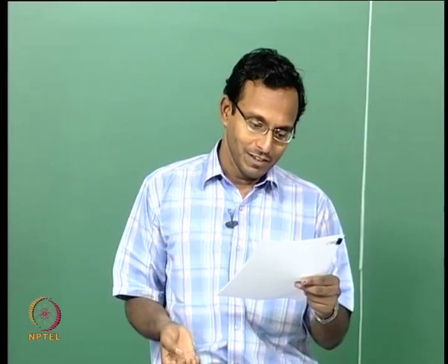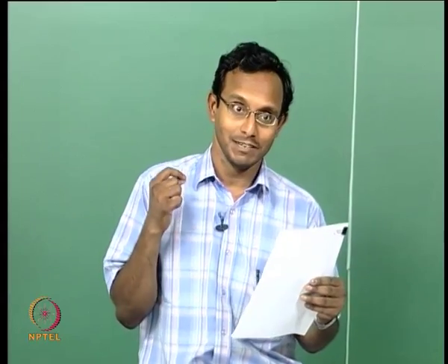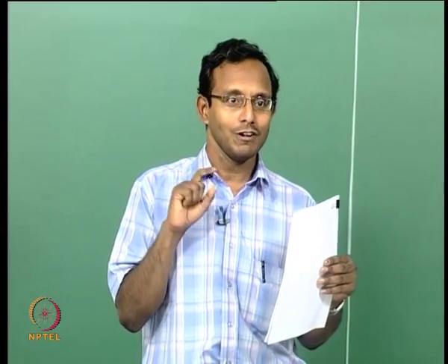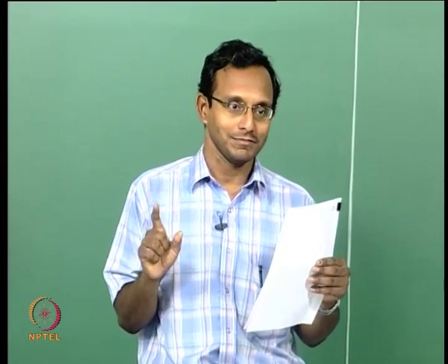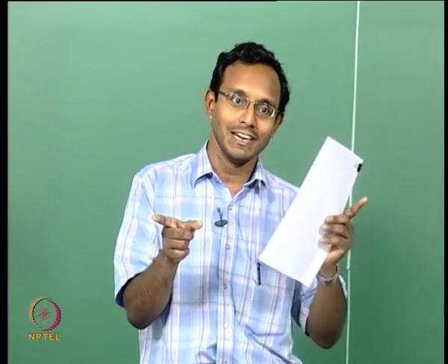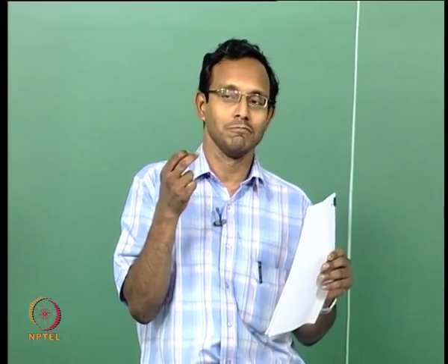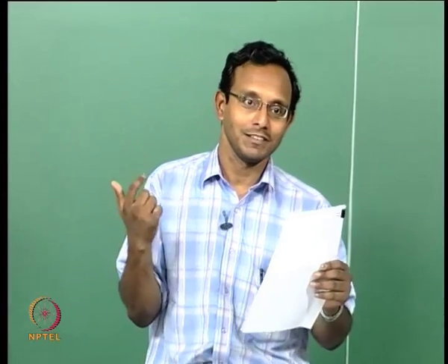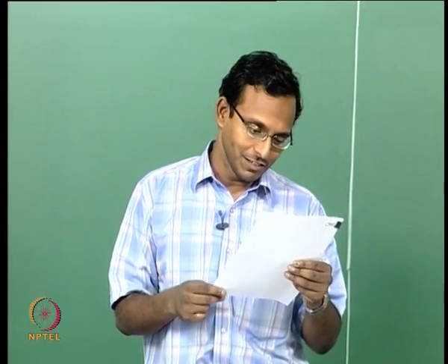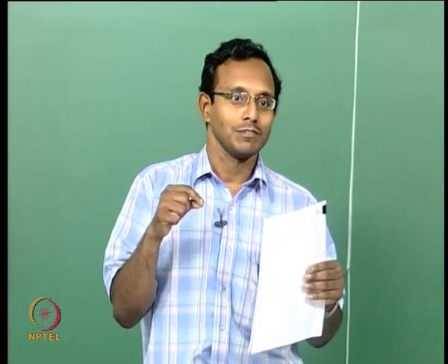When the change is extremely small, that is, I am changing something, but the change is extremely small, then I will either get a very weak oblique shock or a very weak expansion fan, where the expansion fan will not span a very wide delta theta, it will just be spanning very small angles, probably a very small part of 1 degree, something like that. So, in which case it will look like one line. And if it is a weak oblique shock, its Mach angle will be almost mu. How do I know that?